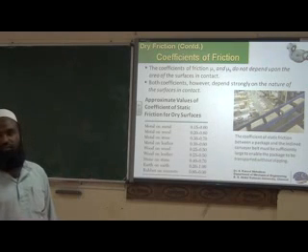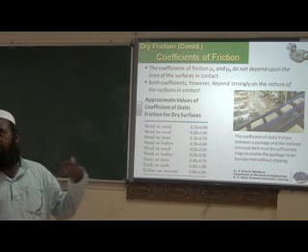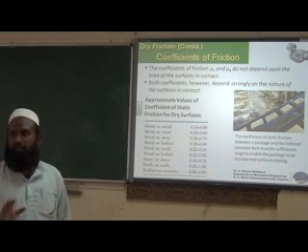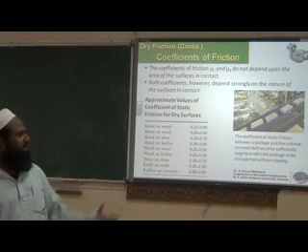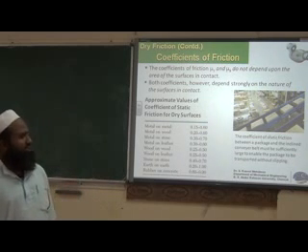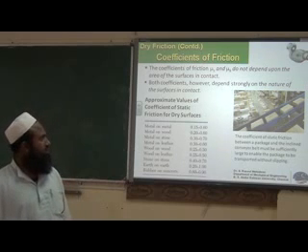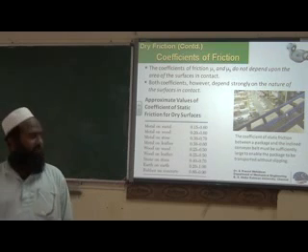The coefficient of friction should be high in a packaging system, transfer line or conveyor line, so that when the package is moving, it should not slip. If it slips, it cannot be transferred. This is one of the applications where static friction is necessary. The coefficient of static friction should be good so that the packages will not slip.